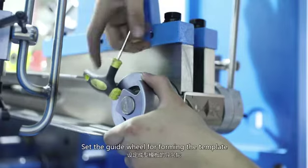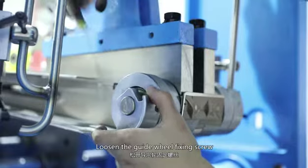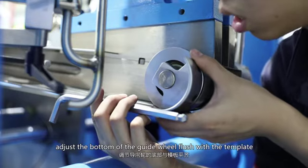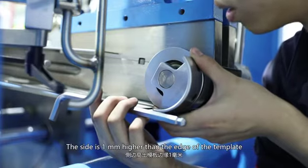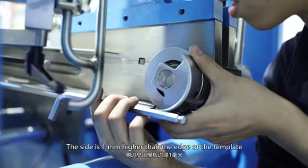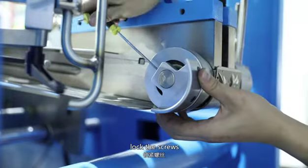Set the guide wheel for the forming template. Loosen the guide wheel fixing screw. Adjust the bottom of the guide wheel flush with the template. The side is 1 mm higher than the edge of the template. Lock the screws.